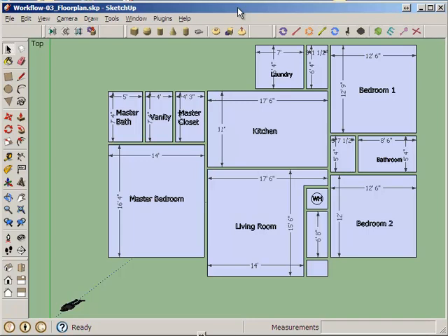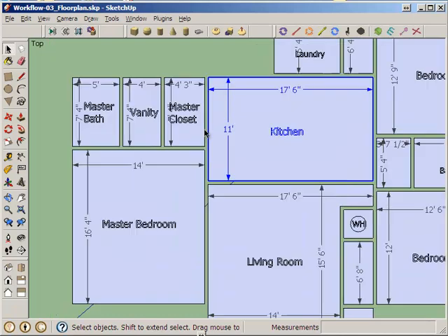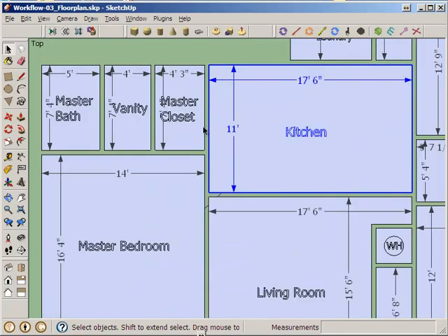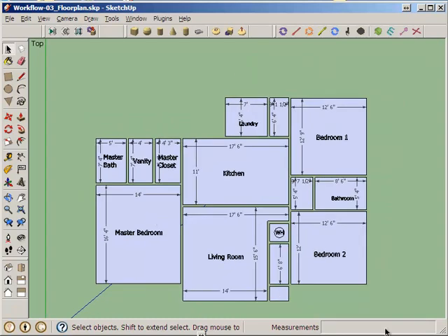We're going to go over putting doors and windows into the floor plan layer. As you know, I made these room blocks and arranged them so that they have 4.5 inches between each one, which is about the thickness of an interior wall, an interior partition.